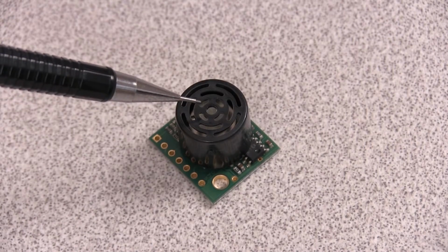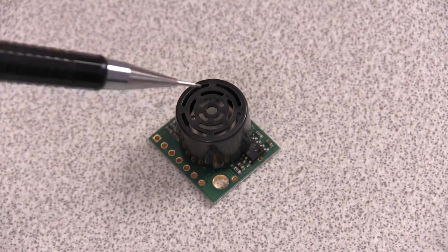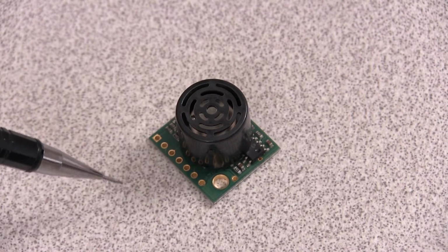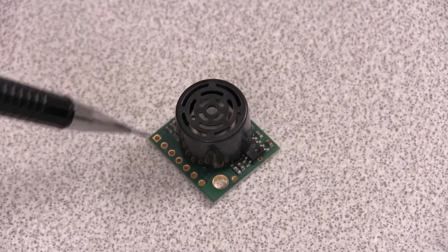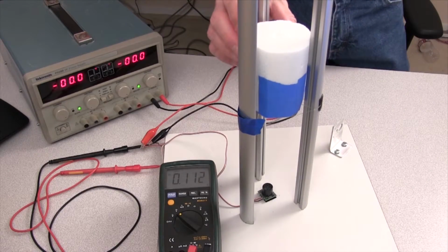This is the sensor we'll use. The ultrasonic signal is emitted and its echo is measured here. The round trip time of the wave is measured, and internal circuitry in the sensor converts that time to a distance. A voltage output is provided at these terminals, which corresponds to the measured distance. This is the system we want to characterize.